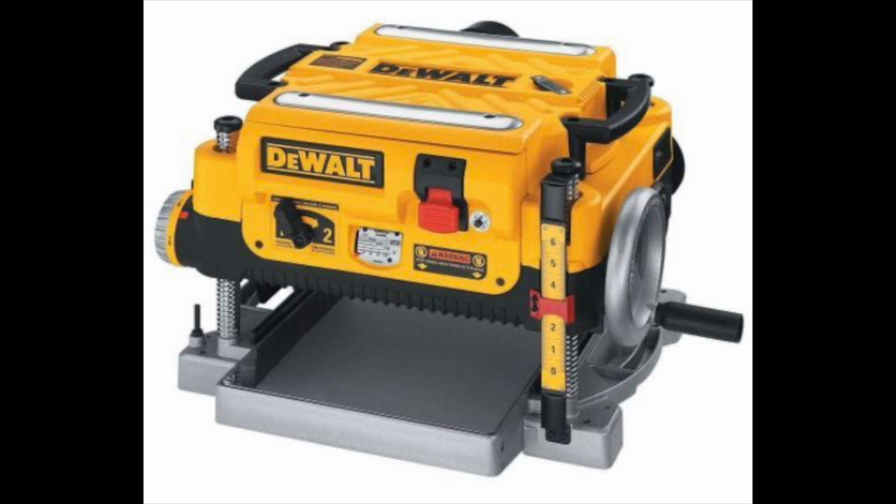A final technique I have used is skip planing. This involves taking light passes with a jointer or planer in order to see the grain. If you like, it can even be used to create a rustic look. After jointing, you not only want to flatten the opposite side of the board, but you also want it parallel to the first side. You can't do that with a jointer, but you can with a planer. That's because your just flattened side that you did on the jointer references down on the bed of the planer. Since the planer's cutting head is above the board, the result will be a parallel side.